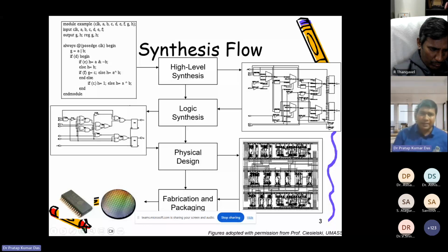Okay, what do you mean by back end? So basically, these are the lowest level things. Finally, what is given to the fabrication, right? A GDS. I hope everybody understands, right? So any design, any chip you do, finally you need to give a package to the fabricator. Like last lecture we had seen, we had multiple fabs. One was TSMC, one is Intel, and in India we are going to have the Tata foundries, and presently we have SCL Chandigarh. So to the foundry we will be giving a GDS.